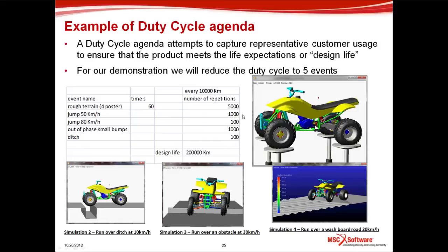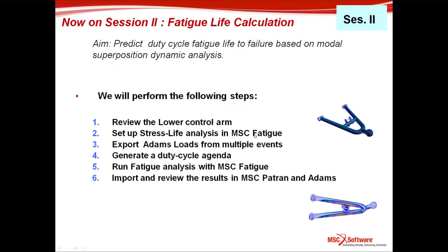Okay, so let's try to represent this requirement in our fatigue product, and let's aim for a design life for the product of 200,000 kilometers. Okay, so we're going to enter now the last part of the demonstration, opening MSC Fatigue and showing how to import the loads, how to generate a duty cycle agenda and run a fatigue analysis with MSC Fatigue. We'll be importing the results and drawing some conclusions.